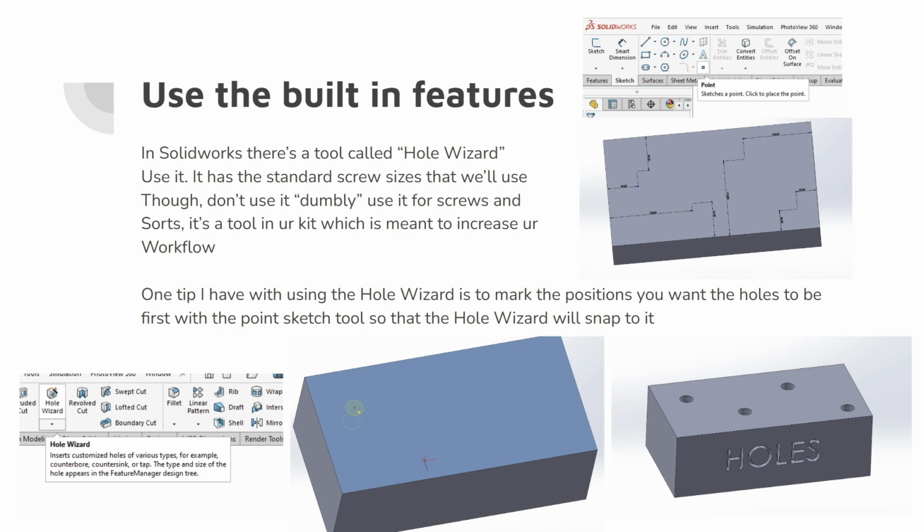Once again, you can just specify the type of screw, and then it creates holes. One benefit of this is there's also a tapered bottom, so it's a bit more realistic. If you want flat countersunk head screws, or all kinds of screws, there's a parameter built in, so you don't have to manually create each sketch. You don't have to make a new surface or a new plane. It's in the properties tab on the left side. Everything important is on the left side, except for simulations, where sometimes you have a guide on the right side, and also the bottom sometimes. Left side. Go ahead, continue.